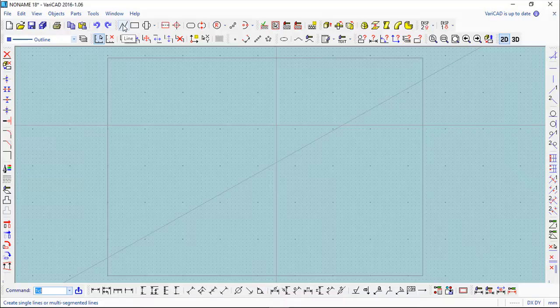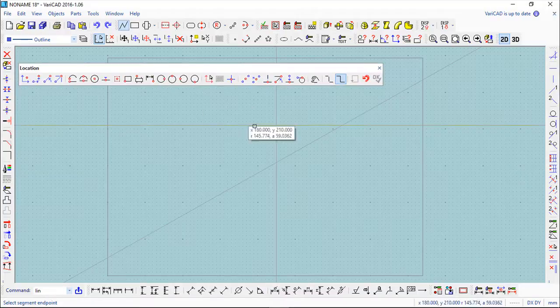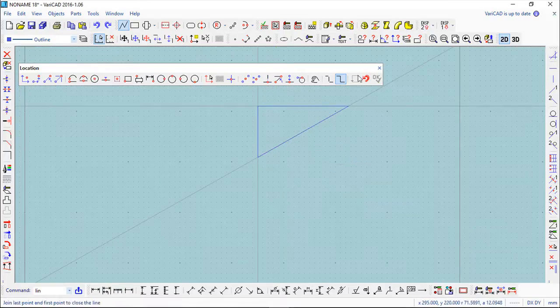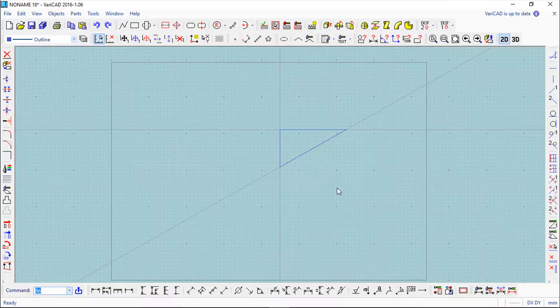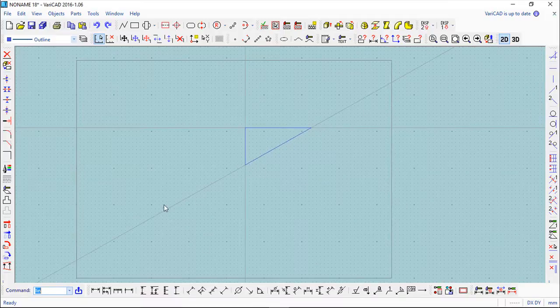You can see the difference. If I create what I can call a normal line, it recognizes the intersection of the lines, and you see, okay, I can click the points and you see the color is different. And another very cool feature of this construction line is that they are not printed. They are just used for construction, to draw. They do not appear when I'm printing to my printer or plotter, whatever you want.